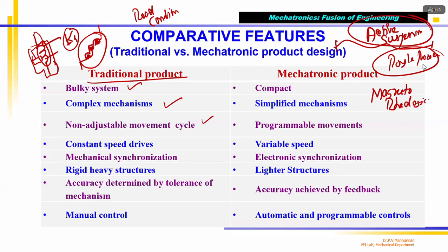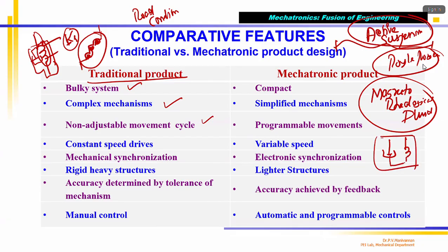Magnetorheological fluid is used because you know that shock absorber contains two parts. One is the damper, the other one is a spring, correct? So together they form a shock absorber in any vehicle. A conventional damper is a piston moving inside a cylinder, both sides fully enclosed, which is filled with oil, correct? In the piston there are small orifices, and when the piston moves, the fluid from one chamber goes to the other chamber, which produces what we call damping force.